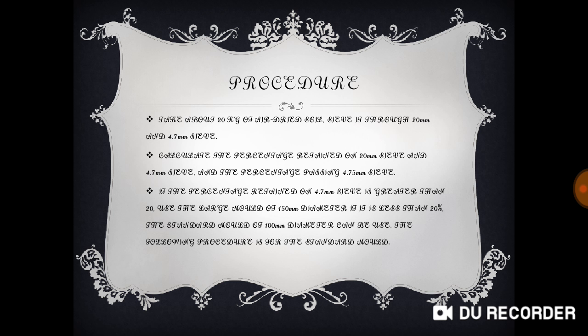So these are the procedure. First, take about 20 kg of air-dried soil and sieve it through 20 mm and 4.75 mm sieves. Calculate the percentage retained on the 20 mm sieve and the 4.75 mm sieve, and the percentage passing the 4.75 mm sieve. If the percentage retained on the 4.75 mm sieve is greater than 20%, use the large mold of 150 mm diameter. If it is less than 20%, the standard mold of 100 mm diameter can be used. The following procedure is for the standard mold.